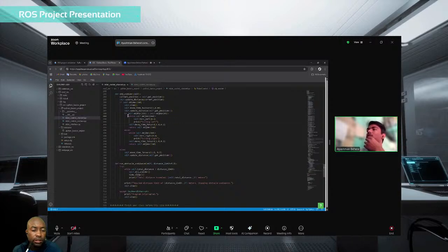But I thought that we can just put a while loop so that every time we turn, we can check back whether the object is clear. We will turn as long as the object is in front of us, and then we will start to move forward. I think the if and else branches are both similar, just turning left and turning right. If there is no object, then we'll just keep moving forward and updating the distance as we go along.